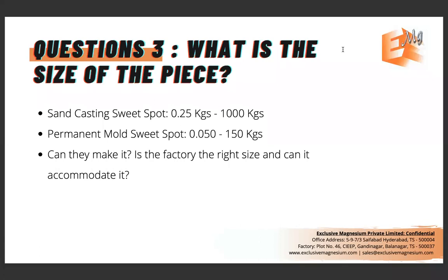Because in sand casting, even a 250 kilo casting or a 750 kilo casting, or in permanent mold, even a 75 kilo part, can sometimes become a challenge for manufacturers. So it's important to understand the factory size that you're working with, and whether they can accommodate it easily, or whether this is going to be a real stretch for them.